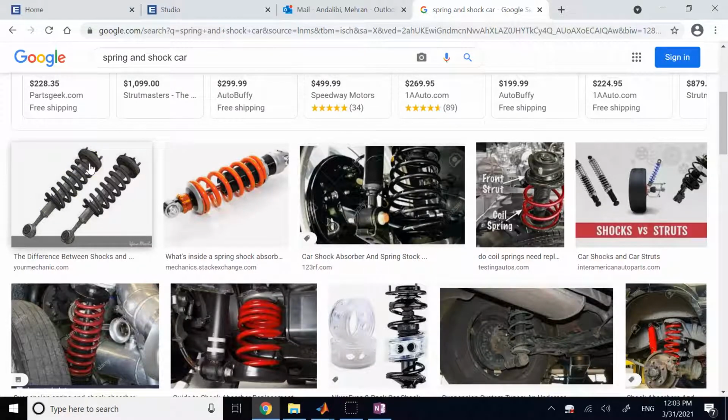To not allow the people riding the car to go up and down a lot of times if you pass over a bump. And the goal of them is to take the vibration away from the people inside the car. We call it vibration isolation. And the goal of the shock is also to damp those vibrations out very fast, so your car chassis doesn't go up and down a lot of times, just a few times, and then the vibration is damped out and dies.